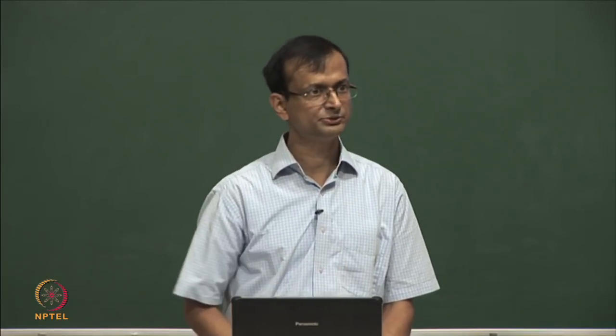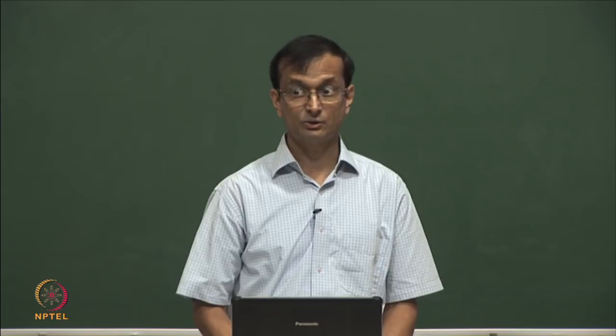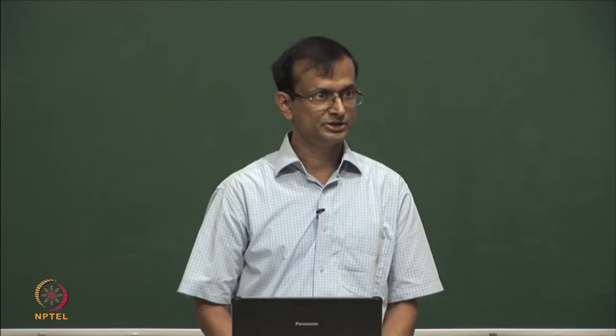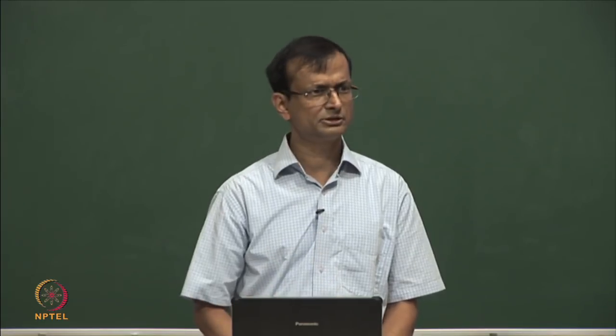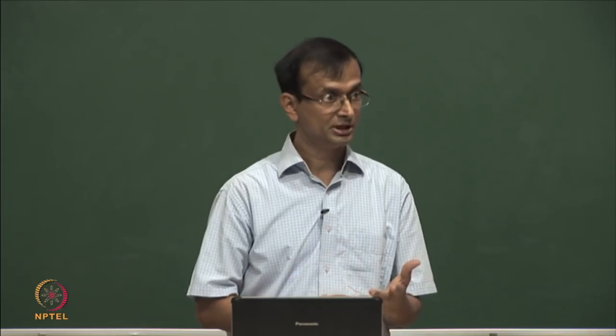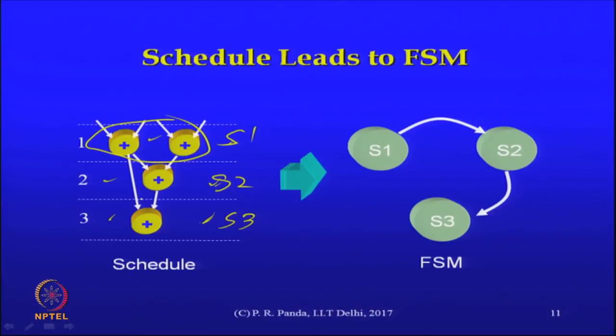The fact that we came up with this schedule means that we took that decision after being aware of these delays. According to the methodology, the clock period is an input to the synthesis process, and the details of the library elements are also visible to us as part of the synthesis process. Therefore, the respective delays are known.